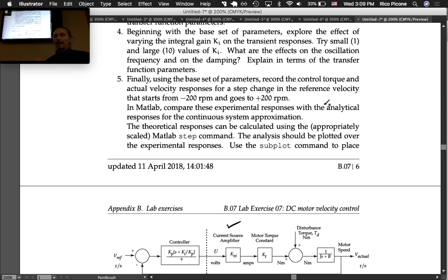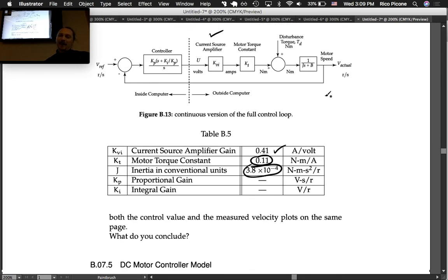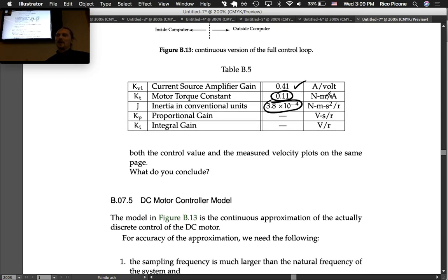But that's the number one annoying thing about simulating actual control responses in my mind: saturated control effort. So saturated control output from the controller. It happens a lot in real systems, and making that happen in the simulation is kind of a pain.